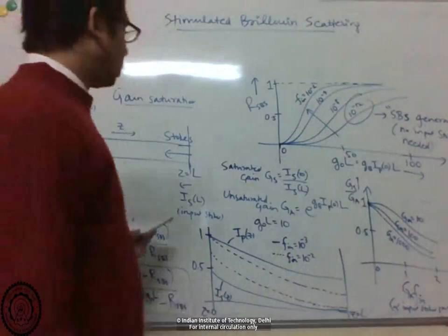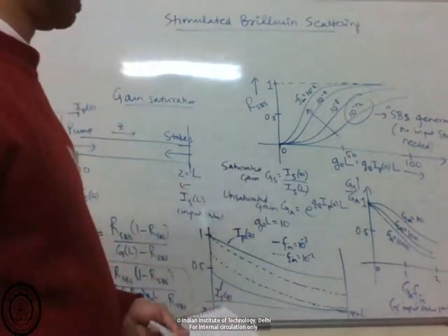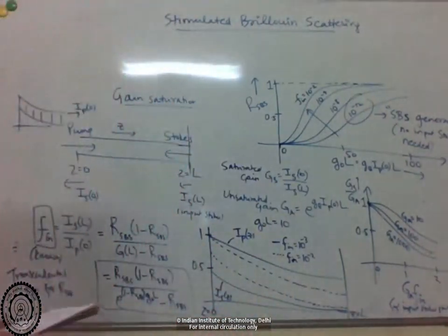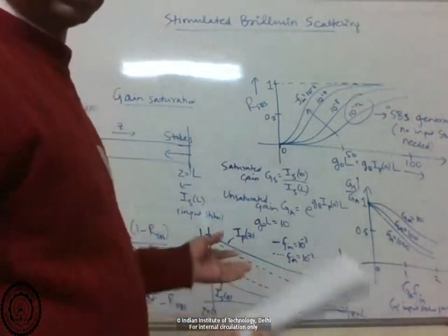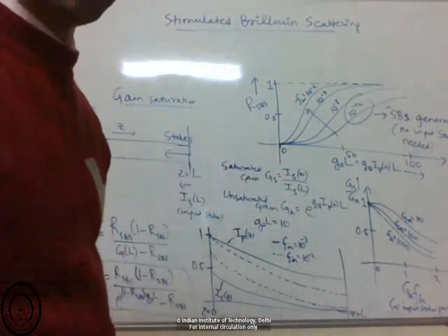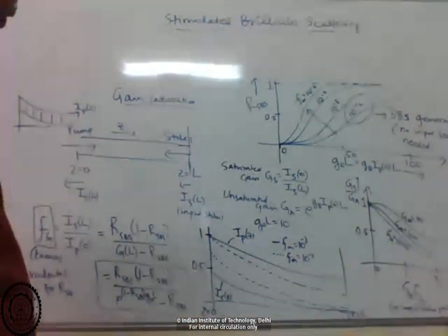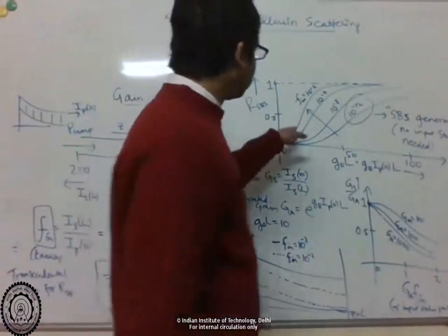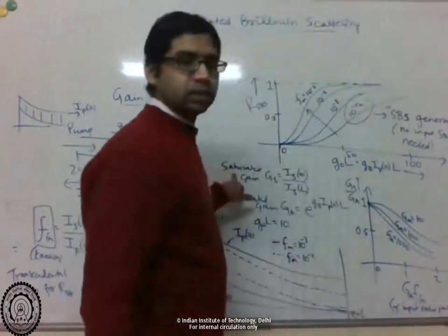Okay, so basically in Brillouin, it's very easy to see these big pump depletion and gain saturation effects. That's why it's important to consider them. Typically, in amplifiers, you usually don't reach the pump depletion limit. But in this case, we reach pump depletion and saturated gain. So why is this leveling off? Because the gain gets saturated.